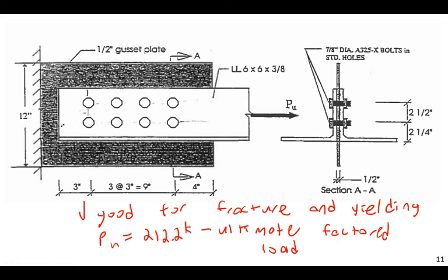Often you do have to pick some sort of failure plane or failure mode when designing or checking block shear. How I'm going to check this one is I'm going to assume that this chunk right here is going to tear out. I'm going to assume that everything here is going to be pulled away, and this section here is going to remain behind. You have to think about this geometrically and physically. I have to assume that this chunk comes out, because I have to make sure that each bolt is being left behind.